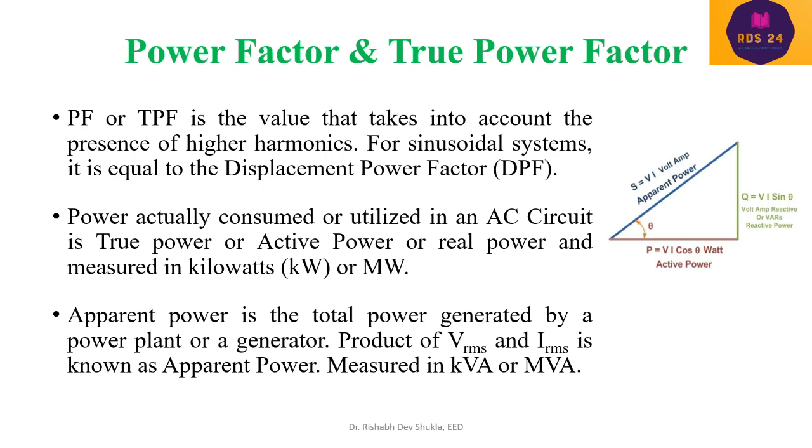For a sinusoidal system, it is equal to the displacement power factor. If you are not considering the effect of harmonics, that means the system is totally harmonic free and the waveform is not distorted, then these two terms are equal. That means when the system is totally free from distortion, then power factor is equal to dPF. Otherwise, when the system is distorted, these two are distinct quantities.